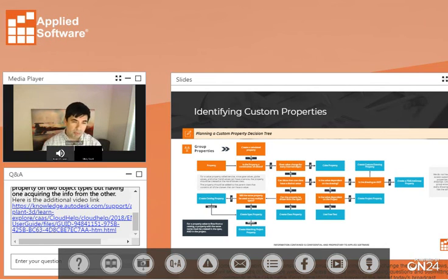Probably the most common place we see this is for the ISO line number, where we want to control the order of the service, the line number, and let's say the nominal size of the spec when it gets labeled on our ISO. There's a help article that shows how to set that up. But that's one of the key places where we use a calculated property, because the single property is a combination of multiple property values.